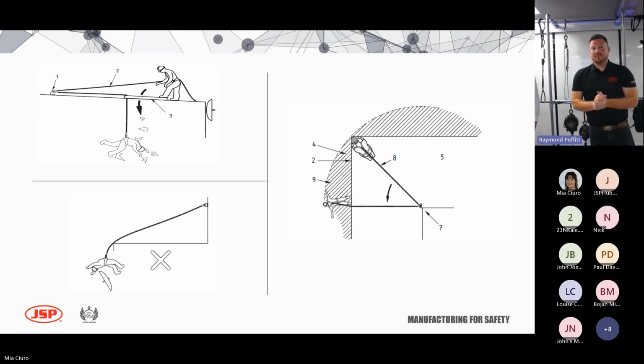On the other side, we have the person that's got to the corner of the roof. Think back to the beginning of the presentation, where the guy in the video has gone to the corner and is now working in the corner, but he can obviously fall off either edge. Again, because he's connected at foot level, as soon as he goes over either edge, he's going to have the chance of swinging. You're going to be swinging on an edge. That edge might be sharp, it might break a standard rope. So again, you need to think about sharp edge tested lanyards in that scenario. And horizontal use blocks will come into play with this as well.